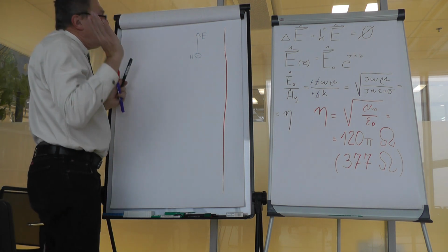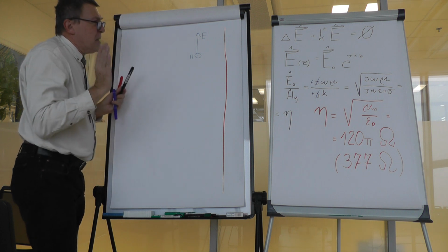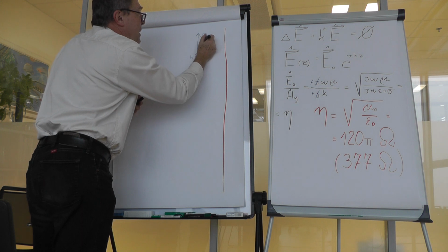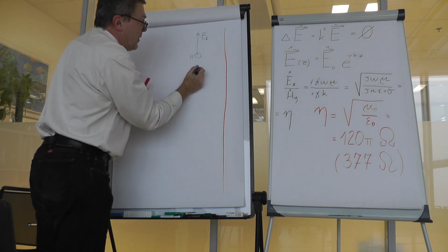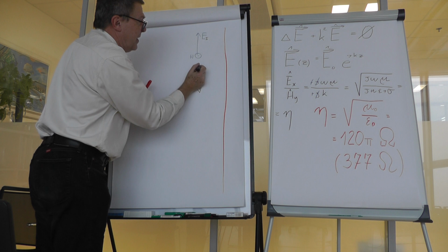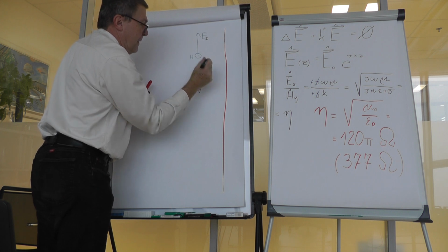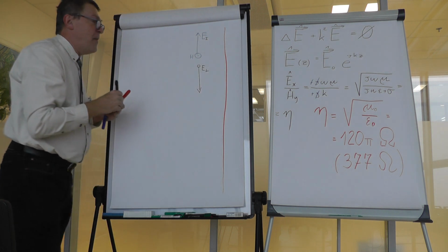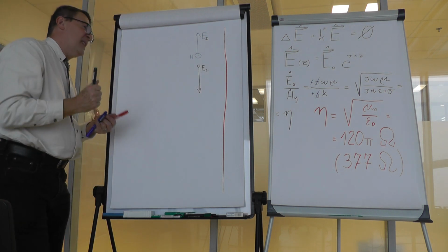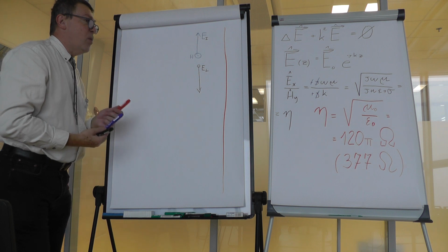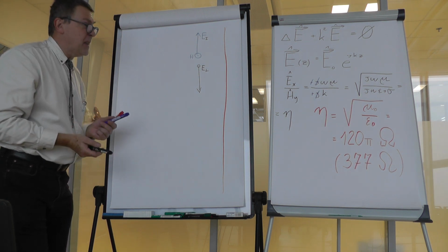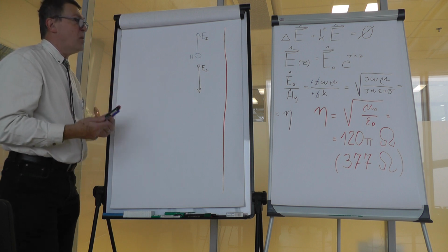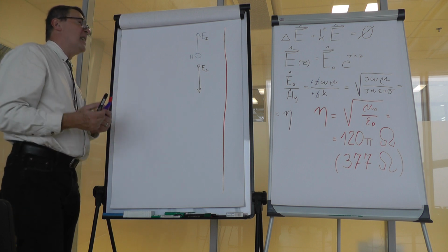So okay, we could solve that problem: we have an incoming wave and we have to create a reflected wave that would have the same magnitude but would be 180 degrees phase shifted, or in the opposite direction. The reflection coefficient would be -1 for this case.